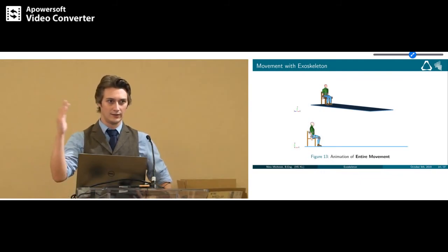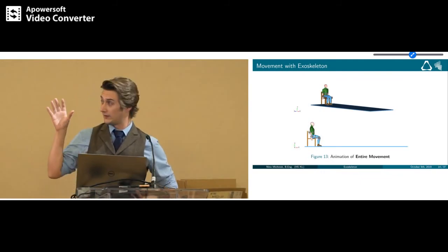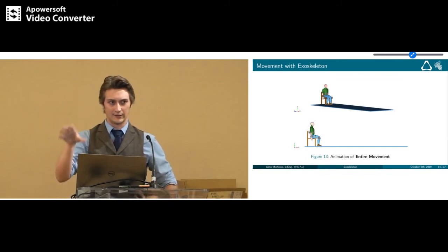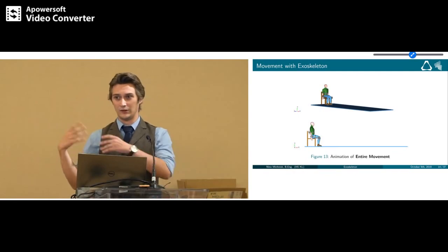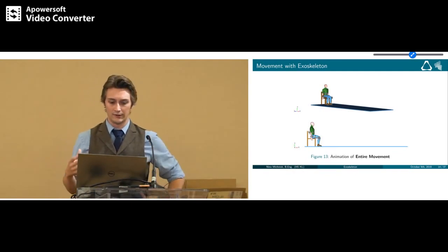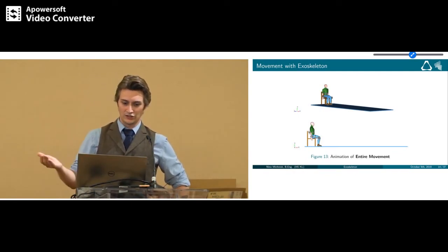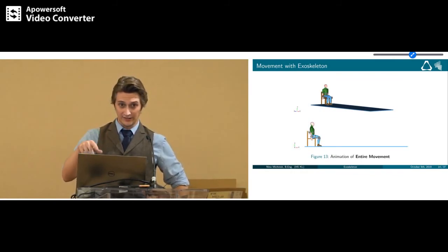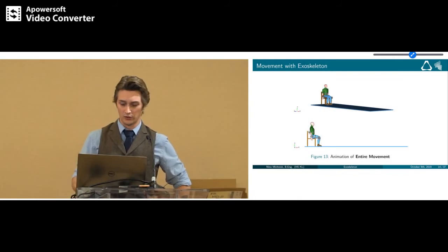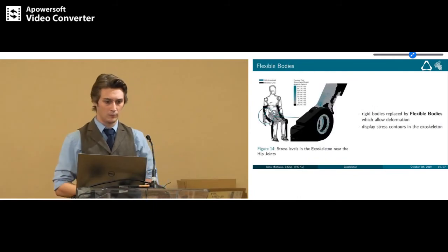And when it reached a vertical upper position, the sensor event detected it and set a constraint. This worked in the first model pretty fine, but didn't work when I used the flexible bodies. So what I did is I exported the angle displacements again and adjusted them a little by hand to have a continuous motion, which I then could use to add flexible bodies to the model.